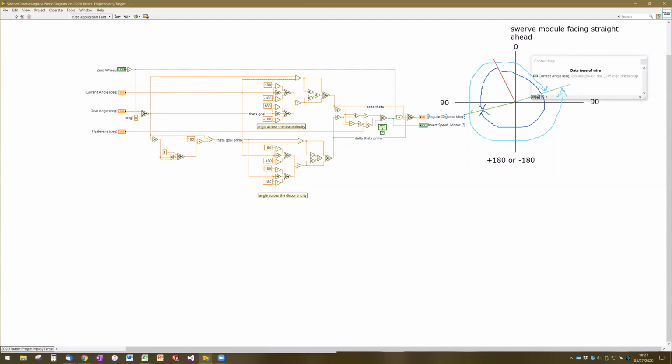And it is important that it is the 100 degrees minus the 30 degrees here, in the sense that we do care about the sign of the subtraction. We don't just care about the absolute value. Because what the PID algorithm needs to know is not just how far away it is, but whether it should be spinning the wheel counterclockwise or clockwise.